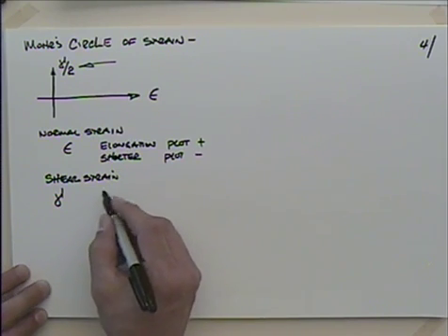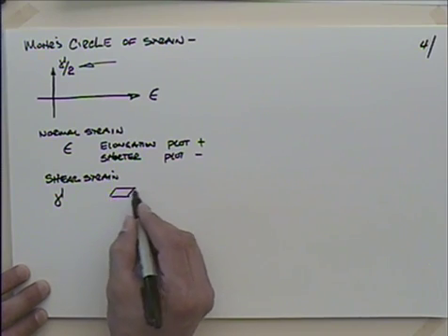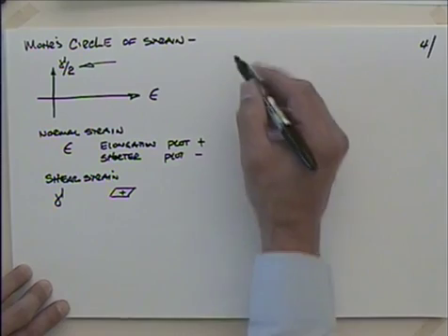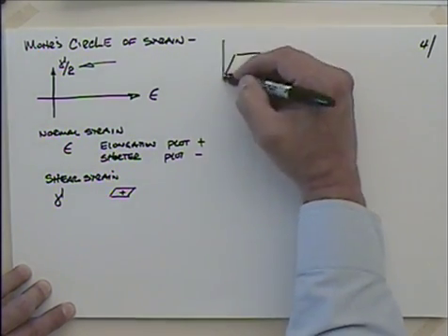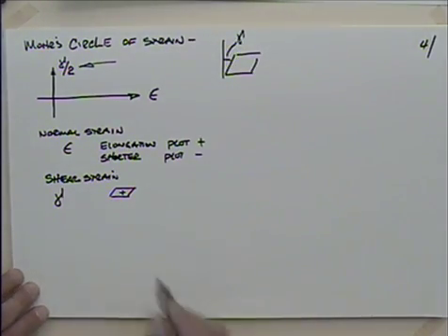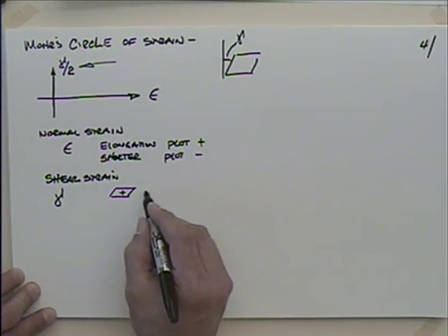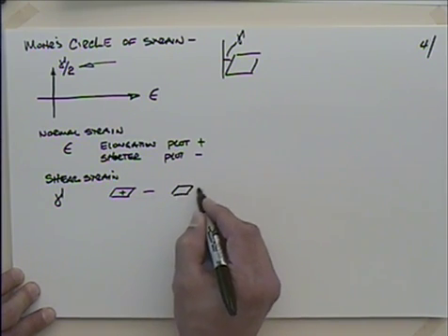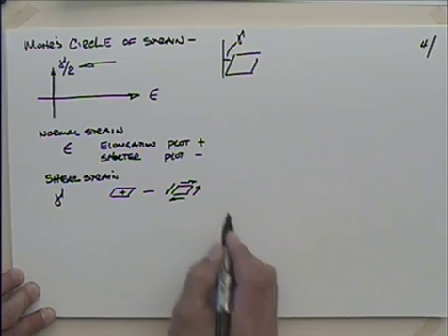But what we do is, if you have strain that looks like this, that's positive strain. Because by definition, remember when we talked about strain, it was the angle that was measured up in here. This is your strain gamma, right? Okay, so that would be a positive angle, which you would get by having what kind of stress? Well, stress that's like this will get you that, right?